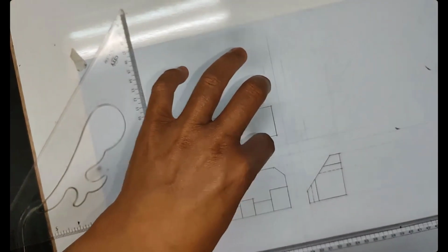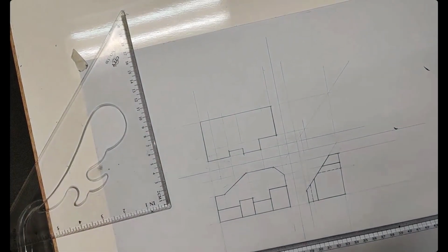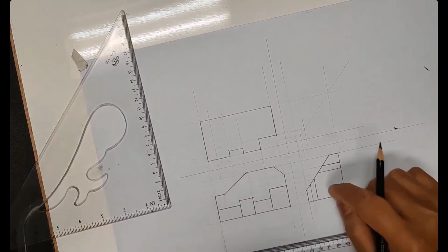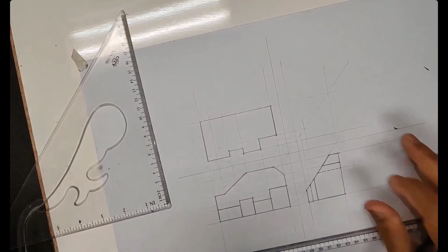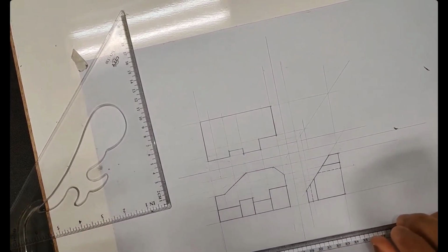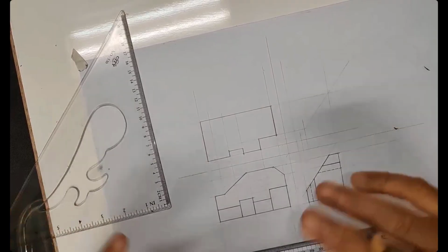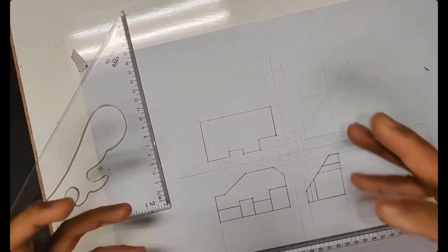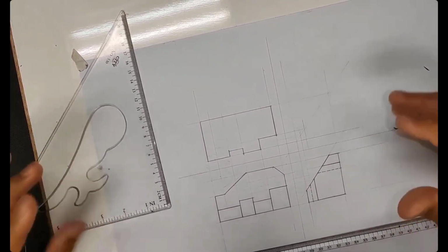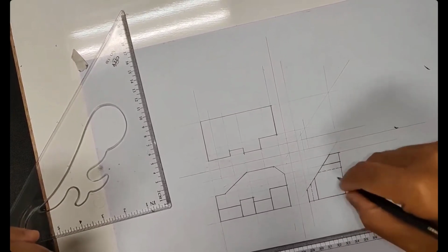Okay, the front view is done, except the drill through hole. The last thing, okay guys, can you see that is a drill through hole? That is the last thing to do. Whenever you are given a question like this, all the secondary parts, drill through hole, counterbore, that's the last thing to do. Make the main modeling first. Understand? If we do this, the last thing we definitely think about is the drill through hole.